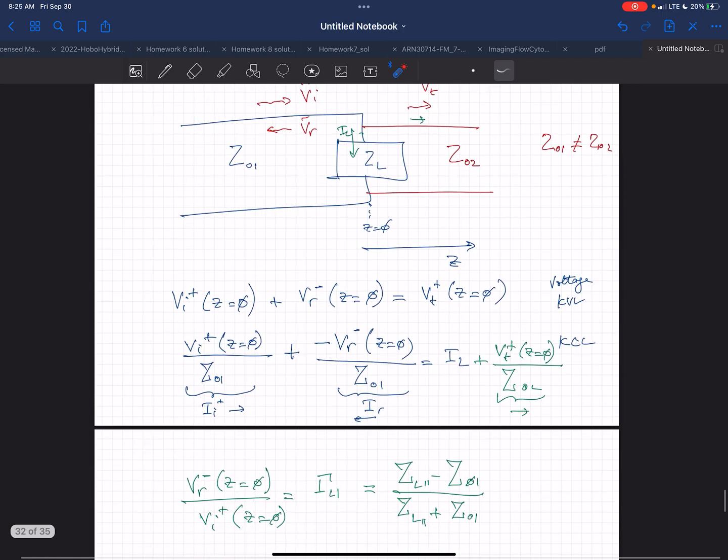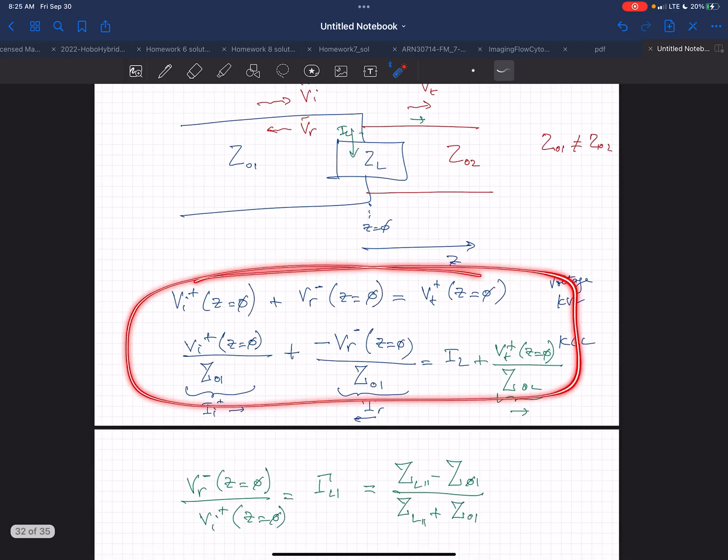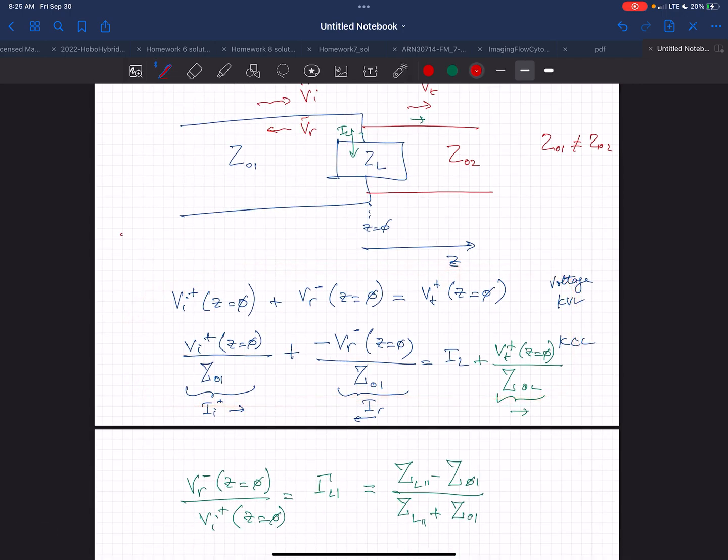So that's what I'm doing, the calculations, to make it easier. Otherwise, you would have to include e to the minus j beta z, or e to the either plus or minus j beta z. Remember, depending on the waveforms, we were assuming we are launching a sine or cosine wave in there from the voltage source with a z component.